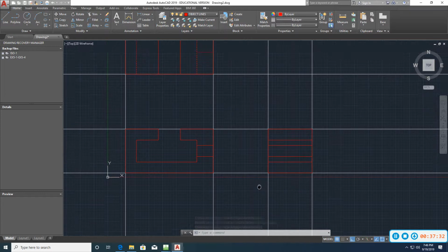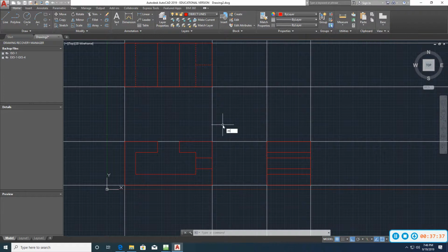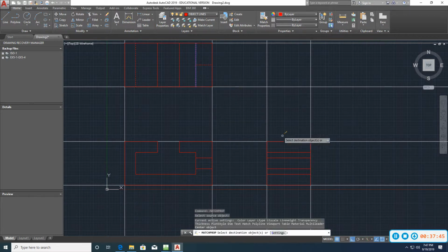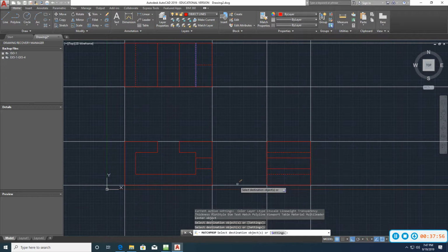Now watch what I'm going to do. Remember that nice command, match properties? I can use that again. Match, P-R-O-P, enter. Select this line here, and select this line. And while we're at it, we can select this line. Okay? All right. Enter.